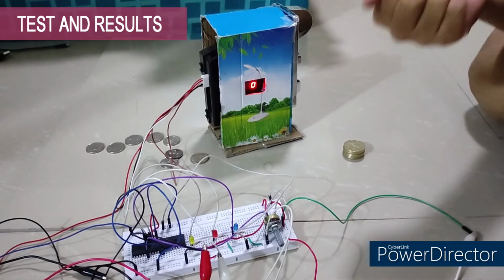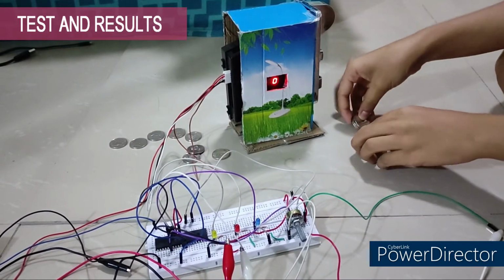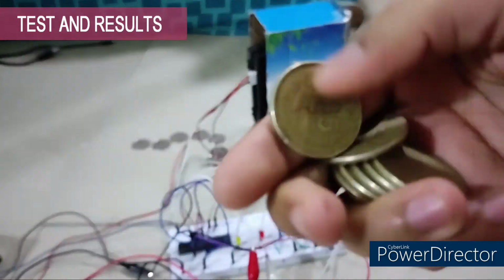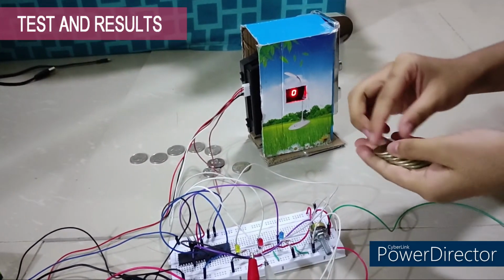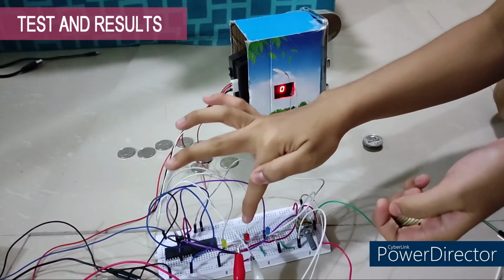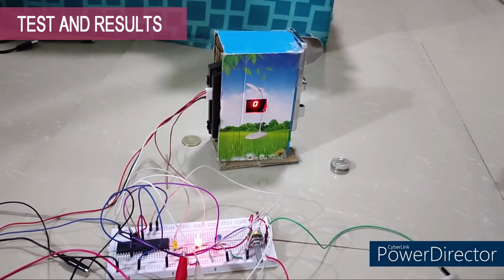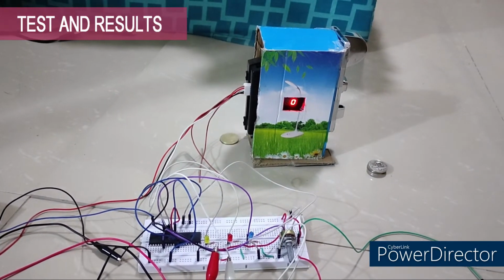Now, for the next proof that our coin acceptor is working and our program as well, we will be inserting an old 5 peso coin to our coin acceptor, as you can see here. Once we enter our old 5 peso coin, the red LED here should light up. So let's start. As you can see, our red LED lights up when we enter the old 5 peso coin.